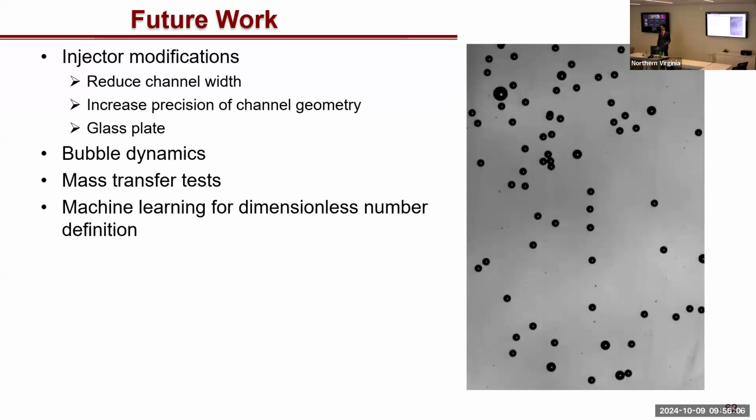One such way of doing this is to use glass as the plate to close the microchannels. Glass has a much higher adhesion factor to PDMS than acrylic does, so it wouldn't require as much pressure from the fasteners. So we would get a more square cross section. We could also consider using laser etching to imprint these microchannels into acrylic or glass, and then use PDMS just as a sealant rather than for creating channel geometry.